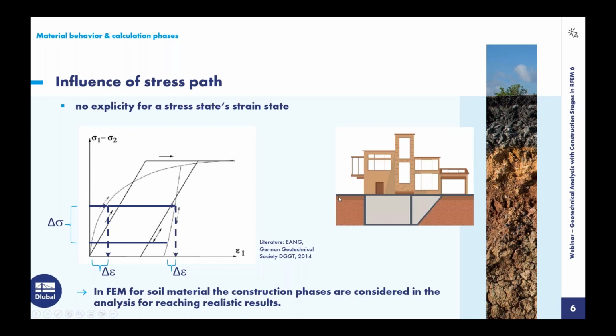You should at first model the whole soil and calculate it. Then you have the geostatic stress. Then you should model the unloading so that you consider that it was before under higher loads and that you are now on the unloading and reloading path.